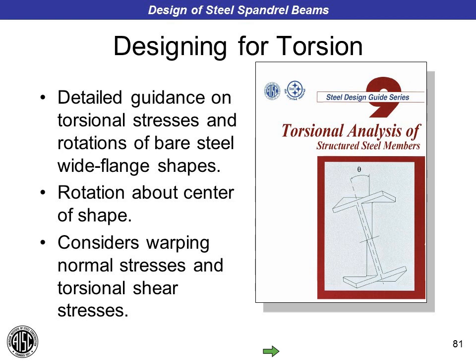But in the case of a spandrel beam, where the beam is restrained at the top by the slab on deck or by roof deck or other framing, the rotation really happens at the top flange of the beam, as we'll talk about in a second. So AISC Design Guide 9 doesn't really address that. So we've tried to do that in Design Guide 22.